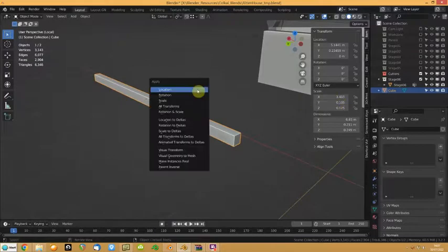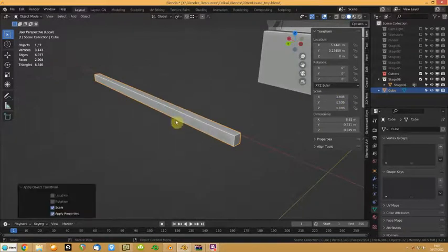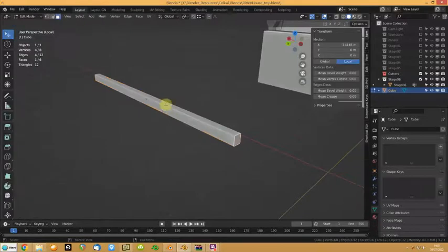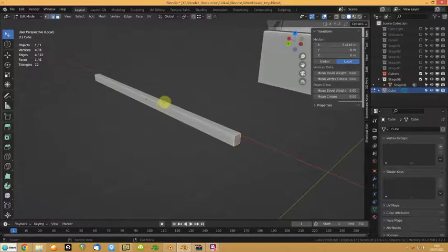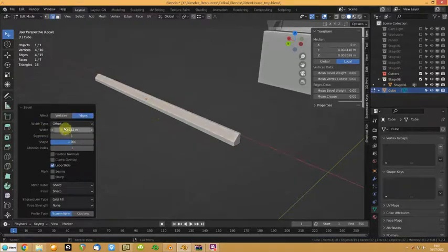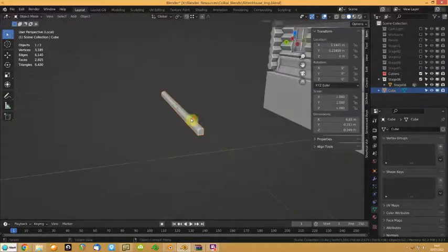So if I do Control A and scale, and you'll see me doing a lot of that when I'm editing, now on a Control B, you get the sort of result you expect. Control B and get a much nicer result. So just be aware of that. Always check that in object mode, and it has to be done in object mode, applying the scale.